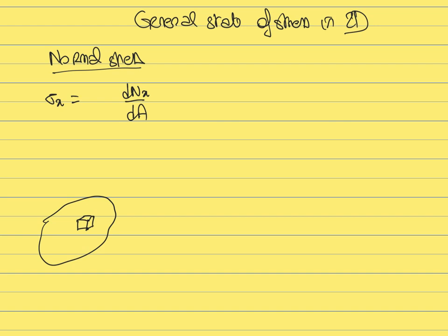This was just a mathematical object that we used to define the stress along a given point O. And we don't want the definition to depend on the size dl that we chose for this small cube. The definition should be independent of this size. So we need to have a cube. We cannot simply define a point, because you cannot have a force that is applied exactly on a given point.